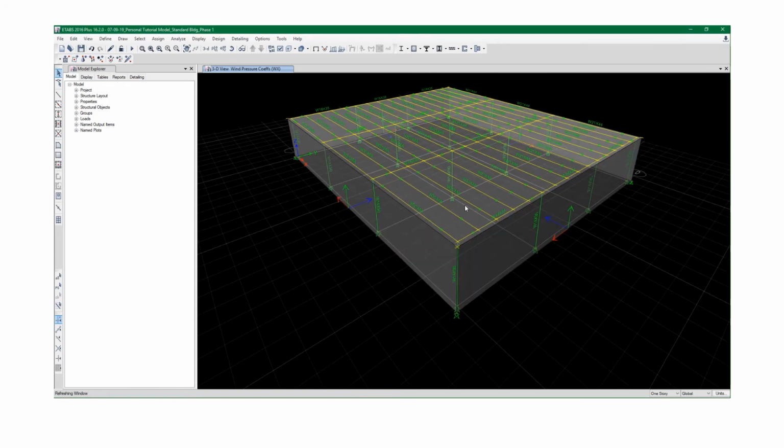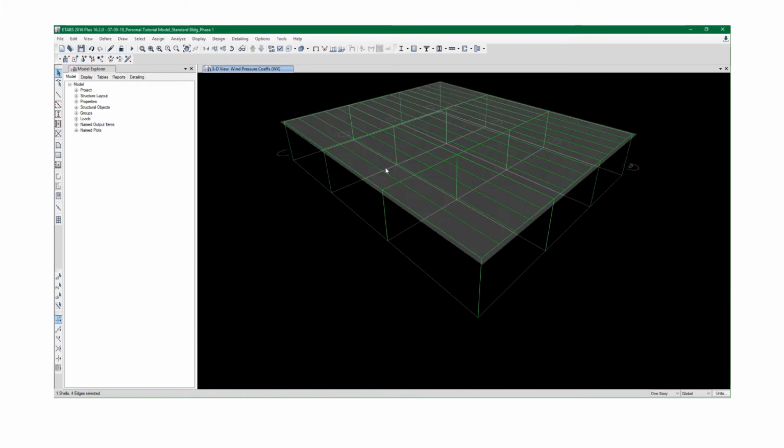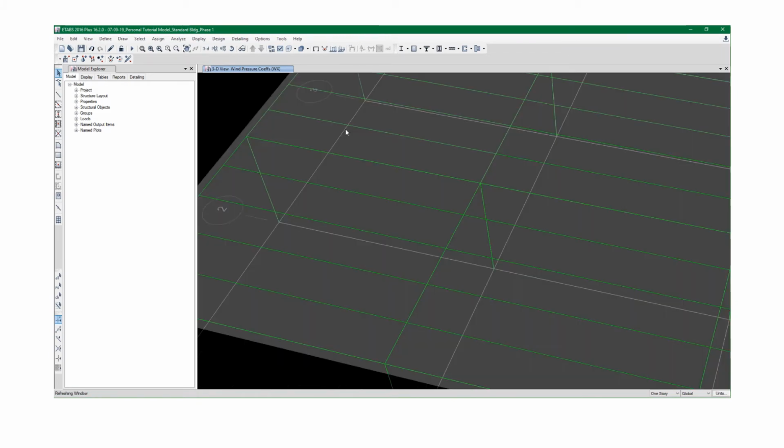Come over here and do the same thing for the leeward side, but I have to put it in the opposite direction so that it goes parallel to the global X-axis, because my local Z-axis is actually opposite to my X. So long story short, read into it. We want the force to go the opposite direction. Once you define it, though, you'll see an arrow that pops up.